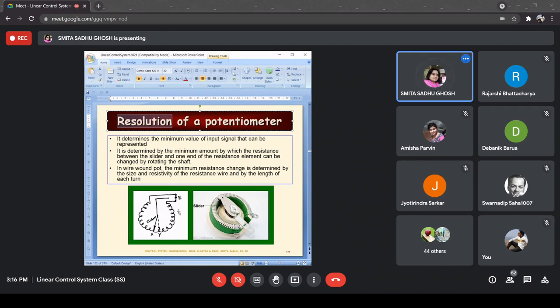So coming back to my sketch over here on this side, you can also see the slider which is being positioned. Now, whenever you have windings like this, there will be a finite thickness of the wire. As a result, you cannot really expect that the slider is smoothly going to give you the voltage at the output.